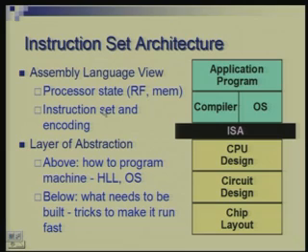Okay. So, as I mentioned earlier, the assembly language view defines what a processor state is, okay, and how the processor state changes from instruction to instruction. As you execute an instruction, the processor goes from one state to another state. So, how is the state defined? State is defined in terms of contents of its memory, contents of various registers and flip flops which are there in the processor.